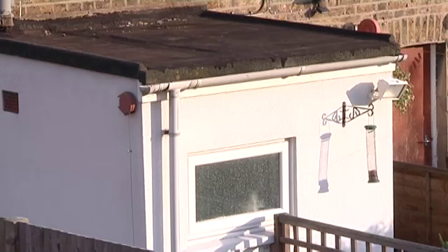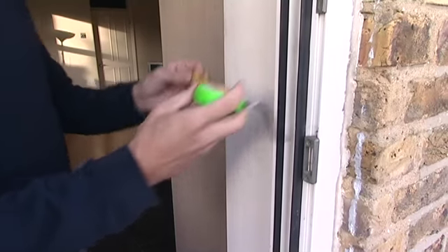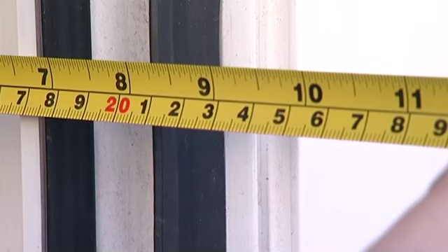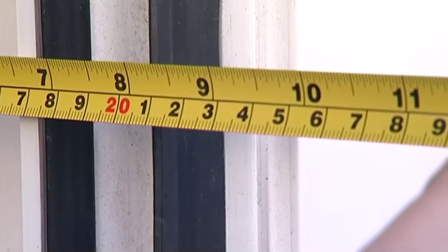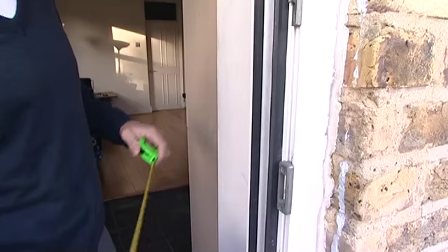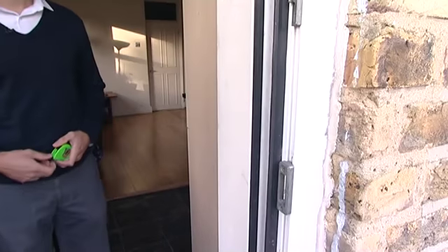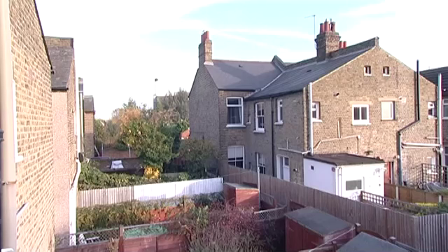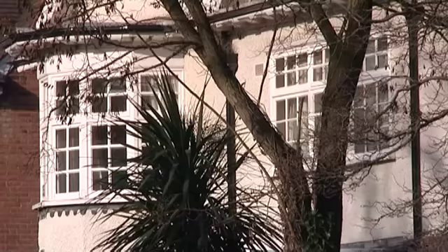If the brickwork has been covered, you can normally tell which type of wall a house has by measuring its width. If it's more than 260mm, it probably has a cavity. Anything less is likely to be of solid wall construction. Before giving any advice on wall insulation, you need to know what type of walls their home has, and you can use these techniques with the customer to find out.